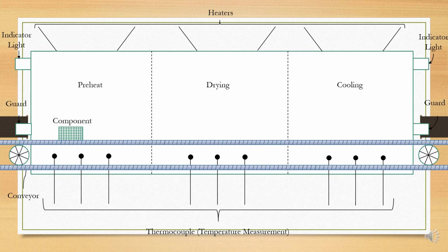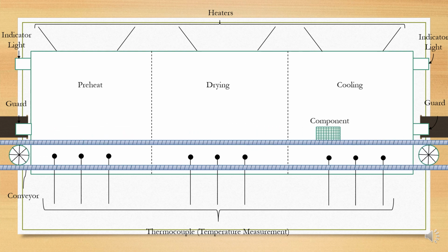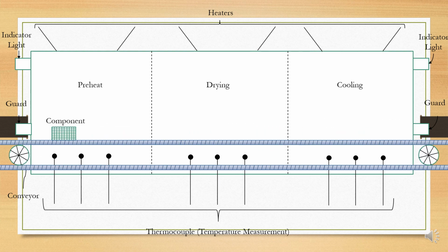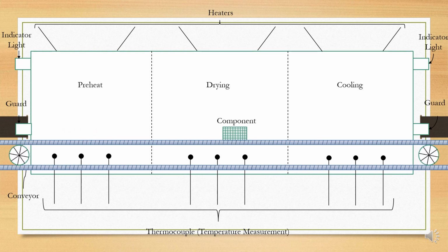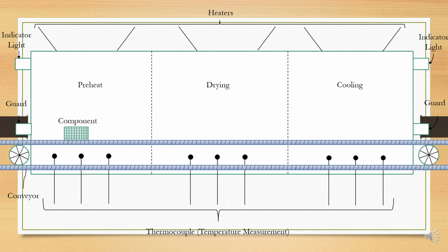These are monitored at different temperatures by thermocouples, which do the temperature measurement. The temperature at the different burners can be monitored and controlled by the operator console unit.